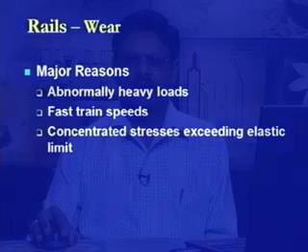So, in that sense, if the stresses which are getting concentrated because of the loads which are coming from the top become so heavy that they are exceeding the elastic limit of the rail section, then in that case also the wear of the rail section may take place. So, this is another reason because of which the wearing of the section may take place.